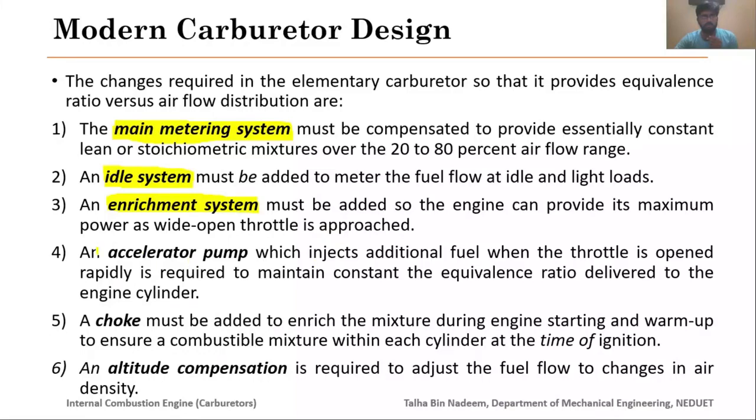Okay, next we have the accelerator pumps. The purpose of the accelerator pump and the enrichment system is quite similar. The only difference is that the accelerator pump usually operates when you have suddenly increased the load, or you have suddenly pressed the accelerator pedal of your car, because in that case the throttle valve has suddenly been opened and a large amount of air is coming through the venturi section, but due to the inertial effects the fuel amount is not increased that much, so the air is not taking out that much fuel. So instead of getting a rich air fuel mixture, you start getting a lean air fuel mixture for a small duration of time, which is not good for your IC engine.